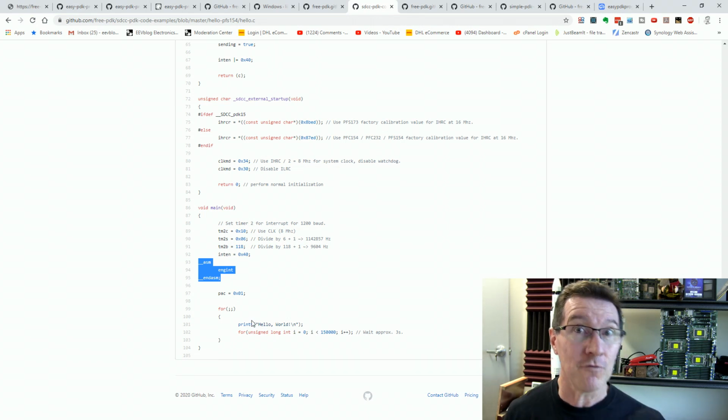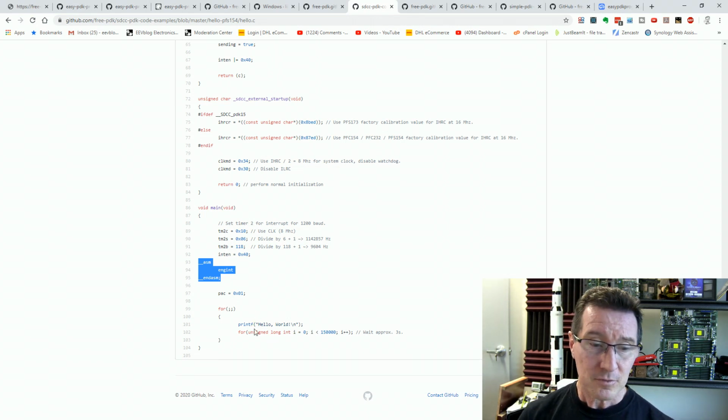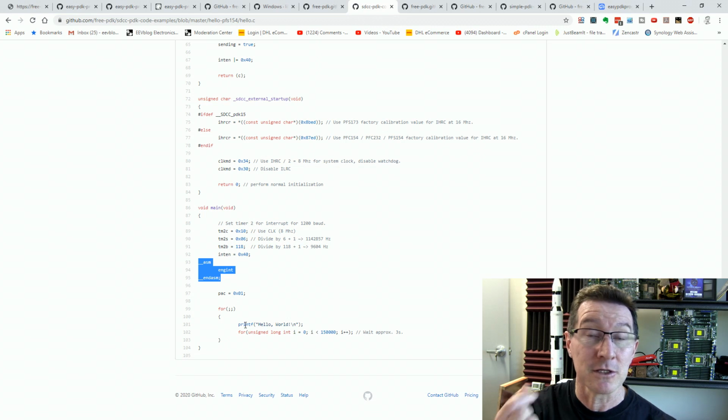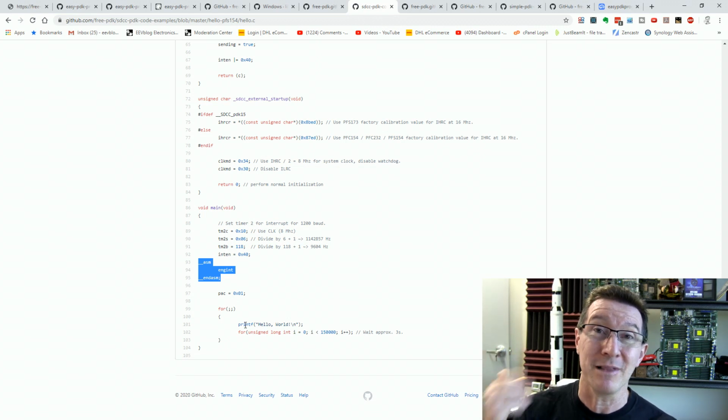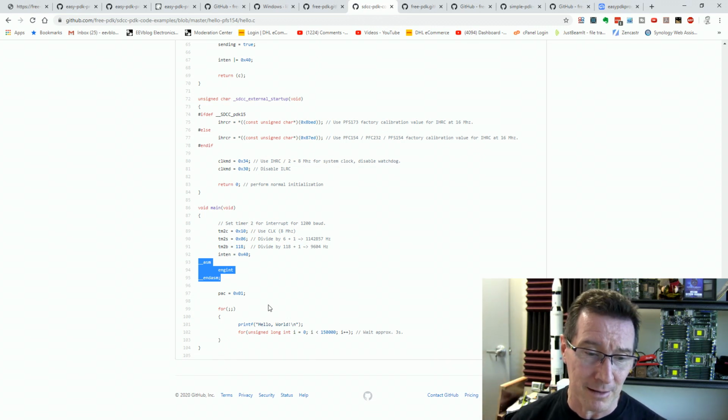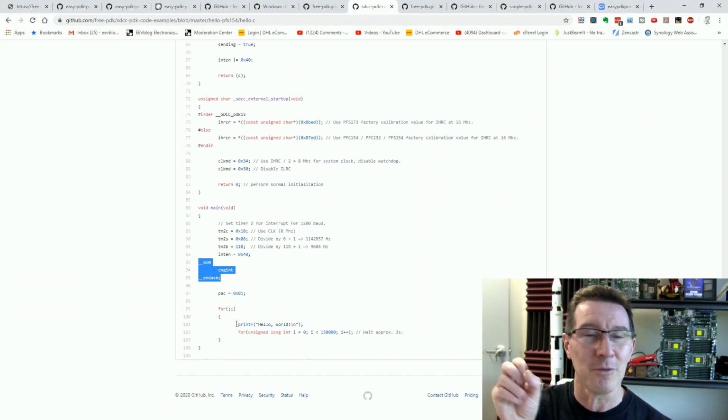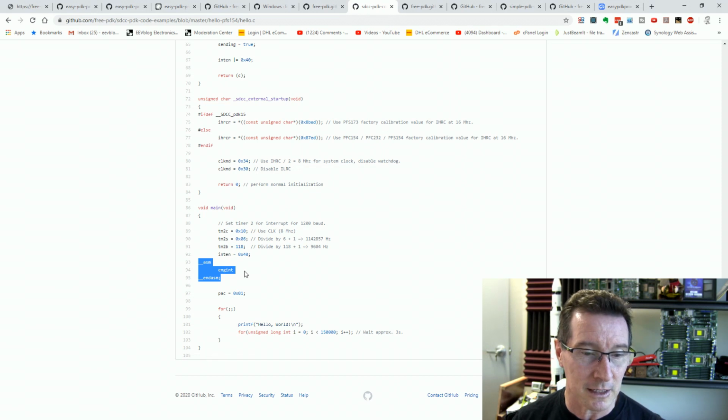Many times I've had to avoid using printf on small micros because it can take a couple of kilobytes of program memory just for printf, for example. So yeah, you can really come a gutser on that. Anyway, we seem to be able to use printf here, but it's probably optimized. A good optimizing compiler will take out stuff you don't need and things like that.